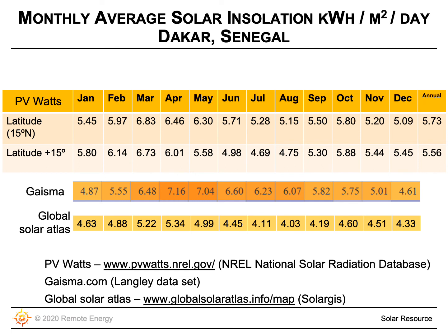And this is because now that the sun is at a higher angle in those months, the collector that is at a lower angle is actually now receiving more direct solar radiation. The very last column in this first data set shows the annual average. So in this particular site, if we had a collector that was angled at the latitude angle, we would have an annual average of 5.73 peak sun hours per day.